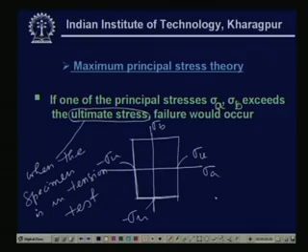The drawback is that the theory takes into account that the ultimate stress value in the simple tension test and in the simple compression test is the same, but it is normally not. With brittle materials, flaws or other material defects are more pronounced when acted upon by tensile stress. But under compressive stress, the material can take more and more load.